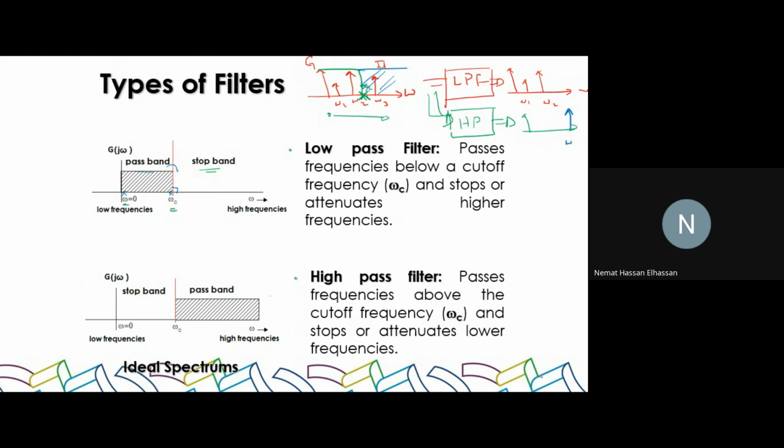So this sharp behavior of having a stable gain and a sharp transition, these are ideal characteristics, which we refer to as the brick wall. They look like a wall, a flat line and a sharp transition from high to low. These brick wall characteristics are ideal, which means realistically, these are ideal if you're simulating, but when you build an actual circuit, it is impossible to have such behavior, an ideal square transition. Realistically, what you'll be actually looking at is some transient behavior, ripple effect.